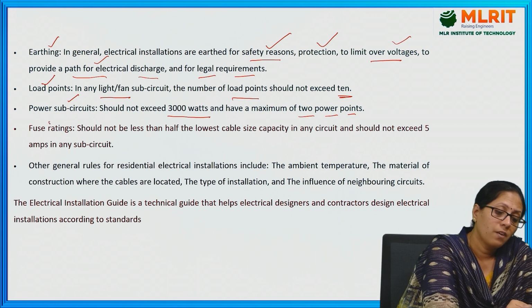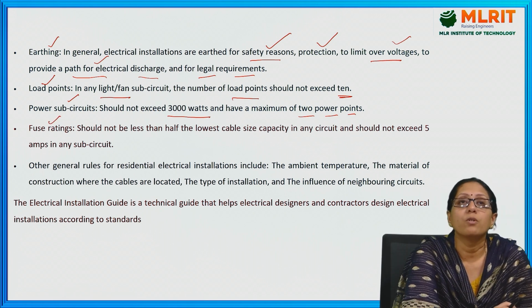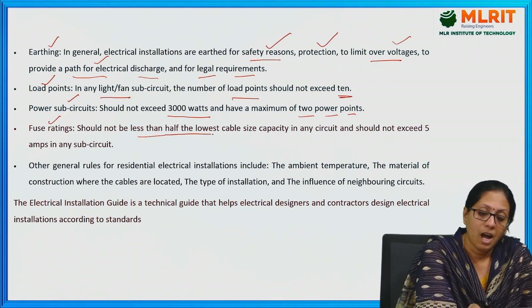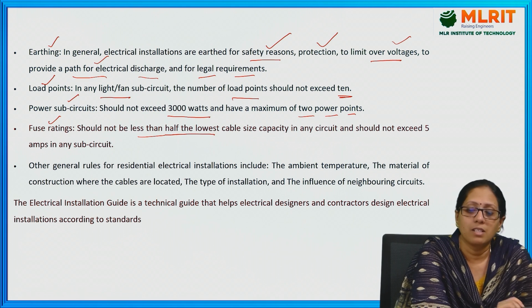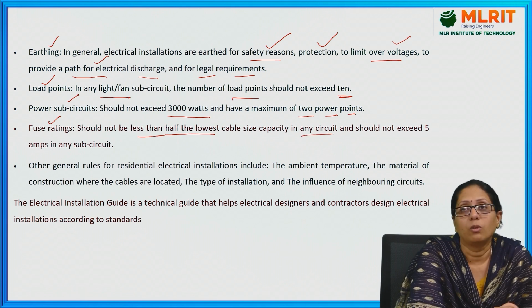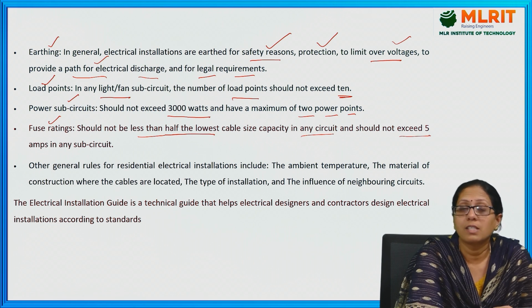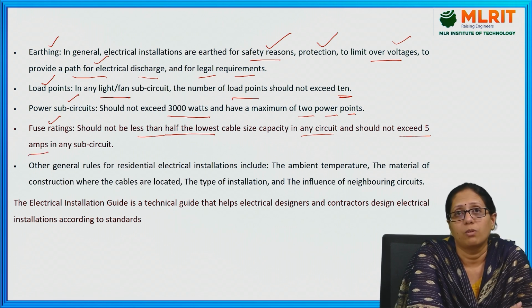The next one is fuse rating. How can we decide the fuse rating? The fuse rating should be less than half of the lowest cable size capacity in any circuit and should not exceed 5 amperes in any sub-circuit.